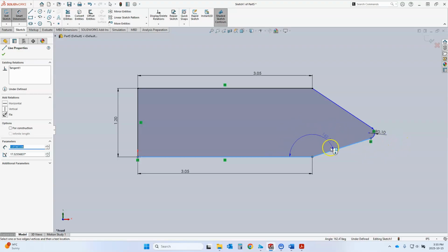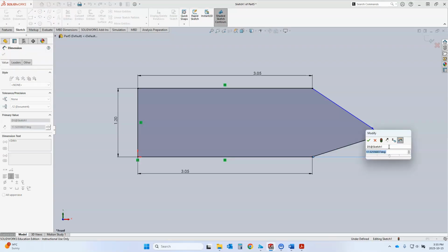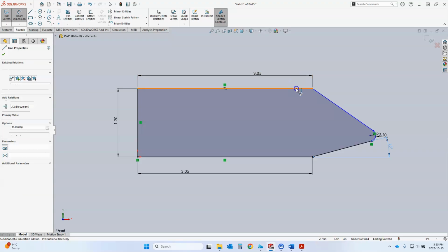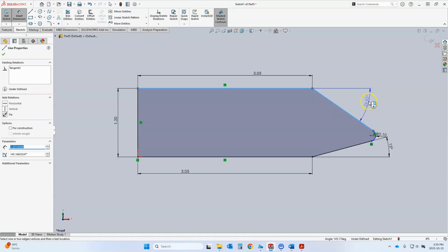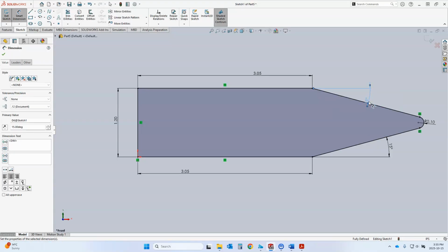So it'll show a different number here, a different number here. So you have to be in this spot, sort of like that. Left click again, that window comes up and we're typing in 15 degrees. So 15, enter, and then do the exact same thing for this top one. So hover, left click, hover, left click, pull it out in this direction, type in 15, hit enter.